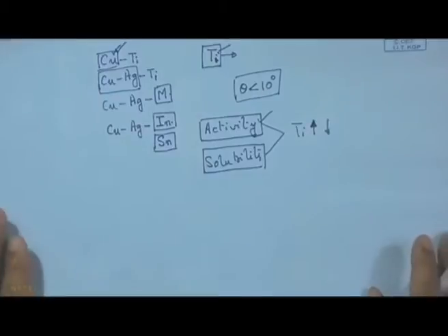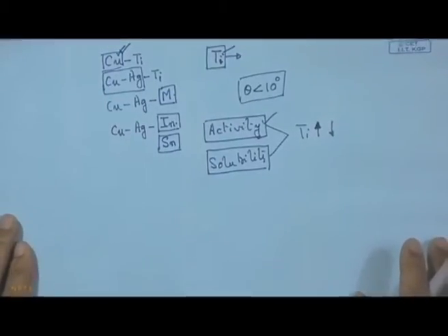So, their basic role is not only to reduce the melting point, or the solidus and liquidus points, that is one advantage, but more importantly to increase the activity of titanium and to reduce its solubility in the parent alloy.